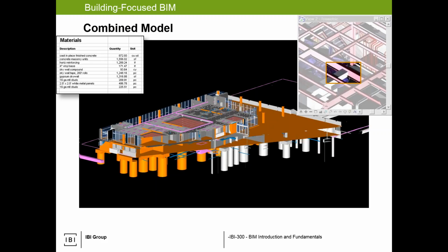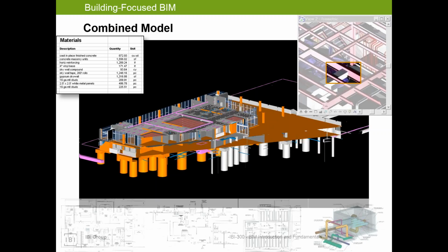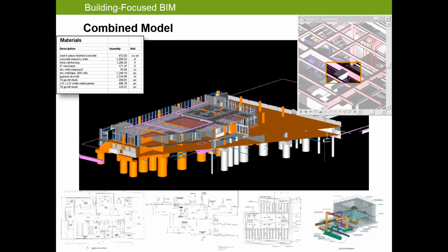You can check for interferences. Do I have ducts that are hitting the beam? If so, BIM's not going to fix it, but it should quickly inform a structural and mechanical engineer that something's got to give right there, because that can't work. Simple communication tool. You can also get plans and sections and schematics and rendering views, isometrics, etc. All of that is a byproduct of the fact that there is a model behind the scenes. And all of this is kind of what I like to refer to as the typical BIM. If we're doing BIM, you're going to get this. The degree of how well you get it is probably dependent on how well the model is, and dependent on project delivery factors of change control and schedule and budget and all those good things.